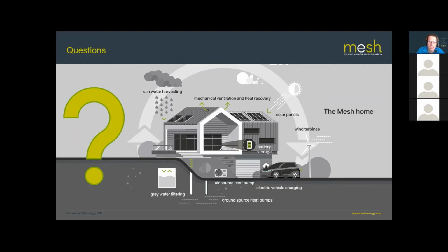You mentioned earlier that 10 to 15 degrees pitch was the optimum, rather than 30 to 40. So, Nada, 10 to 15 is good on a flat roof because of inter-row shading, and because if you go flatter than 10 to 15 degrees, the panels don't self-clean through rainwater. But the optimum angle for actually collecting sunlight is between 30 and 40 degrees. Hopefully the table I showed you, which had all the outputs versus azimuth and pitch, answered that question a little bit.